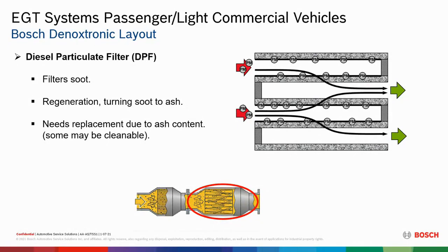So similar to your charcoal grill, if anybody's ever burned charcoal for any period of time, you burn enough charcoal, you're going to have a big ash pit at the bottom after you cook with your charcoal 3 or 4 times. And sooner or later, guess what? The ash isn't going to go away. It's got to be cleaned out. So the same thing with this. Most light duty commercial vehicles and passenger cars, they need to be replaced. There's not too many that are cleanable until you get to medium heavy duty trucks. So keep that in mind. It's a replaceable unit in most cases once the ash load gets to a certain amount.